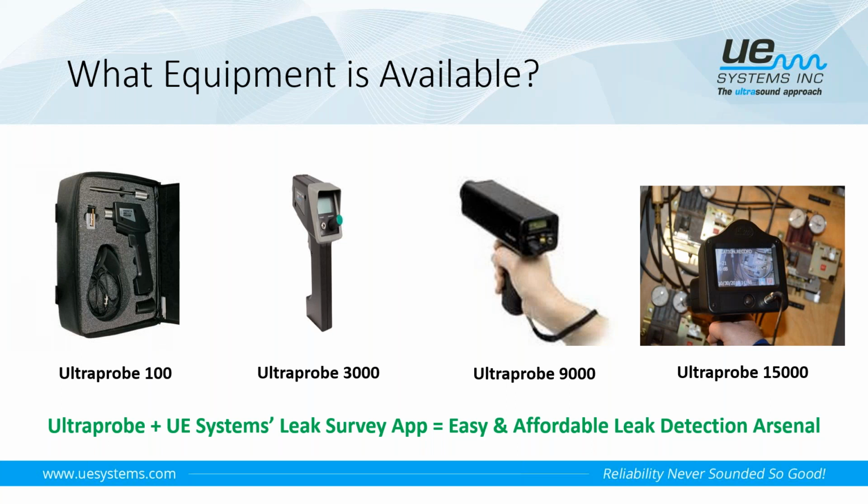And then the last model is the UltraProbe 15000. It may be a little overkill for compressed air leak detection, but we do see a lot of people using it for that, simply because it comes with your standard airborne scanning module as well as a long-range module. So that long-range module has a distance away from the source of the sound, or the leak in this case, of up to about 90 feet away. So it's very well suited for facilities where you have overhead compressed air lines. We can just simply walk along the floor, follow that line using that long-range module, and we're able to pinpoint leaks just by standing on the floor.